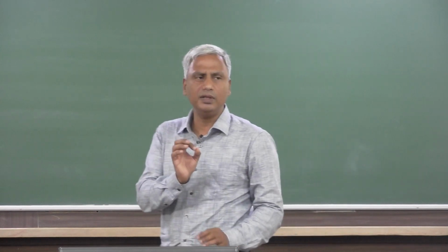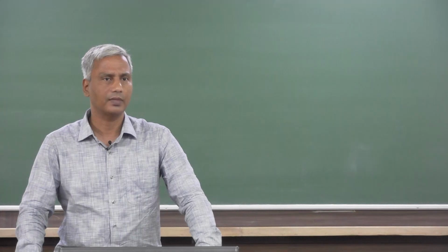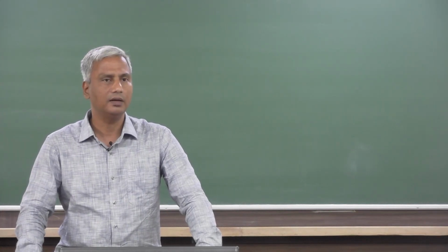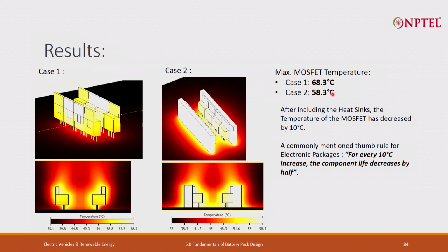Now, even though the failure temperature is 70 degrees centigrade, it would not have failed, but by providing a simple heat sink, the temperature has come down to 58.3 and the life of the MOSFET has become twice.